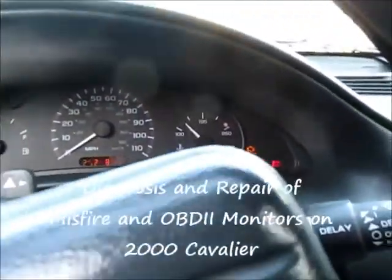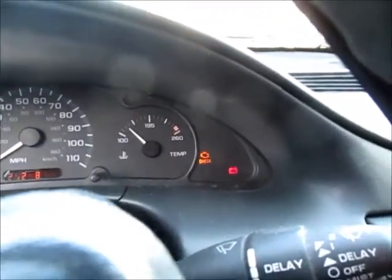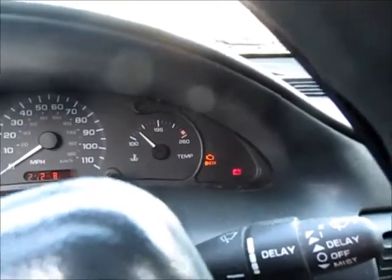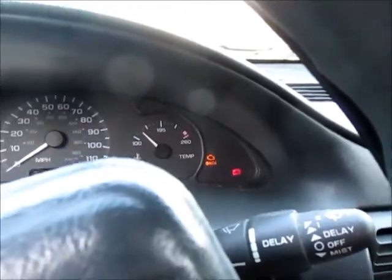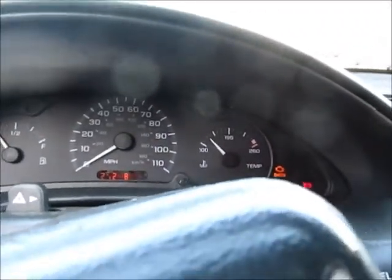Okay, so we're working on a 2000 Chevy Cavalier with a misfire, and the engine's really running rough. And when it gets that bad, the check engine light will actually start to flash. The reason it does that is it's warning you that it's destroying the catalytic converter, because you have a lot of raw fuel going into the cat when the check engine light flashes. So you don't want that to happen. So we're going to diagnose it and fix this problem here today.